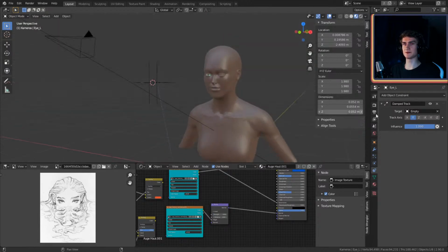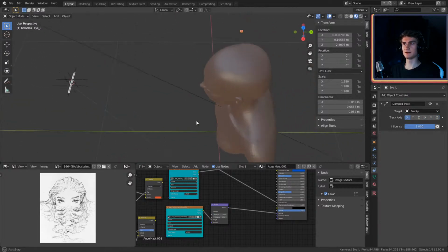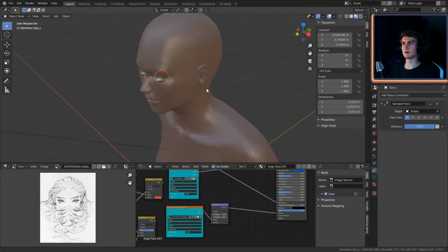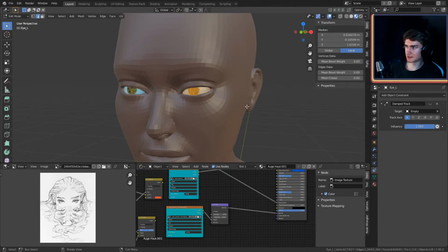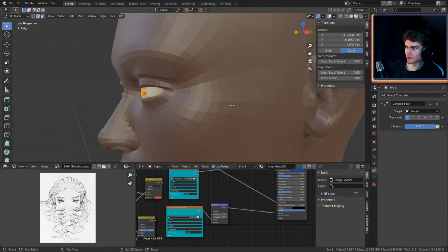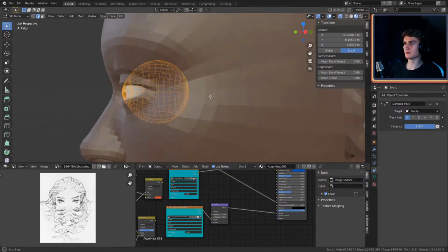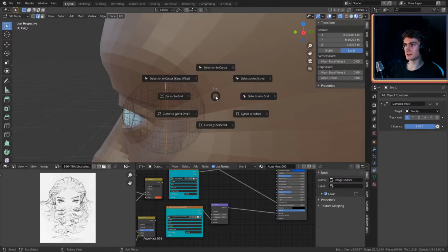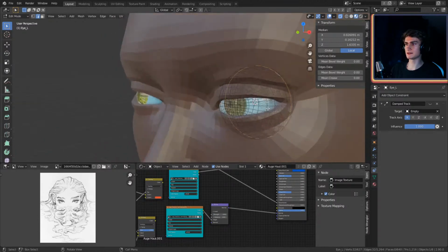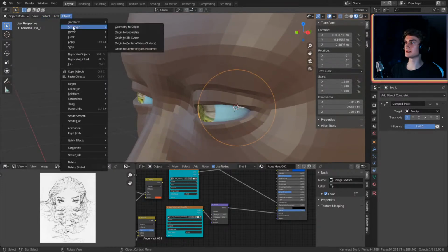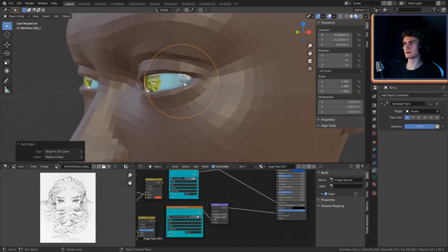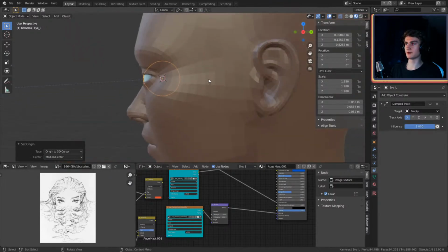As you can see, it moves somewhere else, but we have to change the axis. And I think the anchor point is somewhere else down there. So what we have to do is go in here, select everything, and put the anchor point, or the pivot point, in the middle of the eye. So we'll say cursor to selected. Now it's in the middle of the eye. We can say object, set origin, which is the pivot point, origin to 3D cursor. And now it's in the middle. So this orange dot right there determines where the anchor point is.